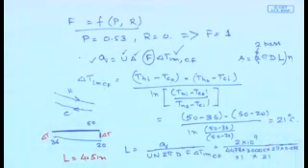So, in order to have this heat transfer process, you have to have 30,000 pipes in a 1 to 2 shell and tube heat exchanger. So that means one shell pass and two tube passes with steam condensing on the outside of the tubes at a temperature of 50 degree, or rather maintaining a temperature of 50 degree throughout the length of the tube, with the heat transfer coefficient specified as 11,000.